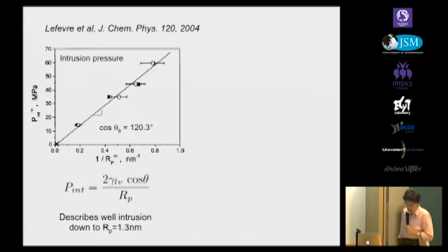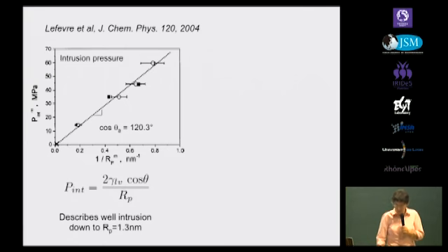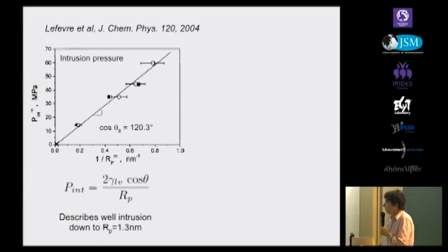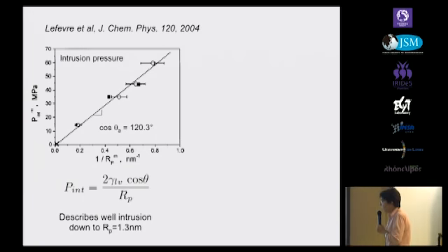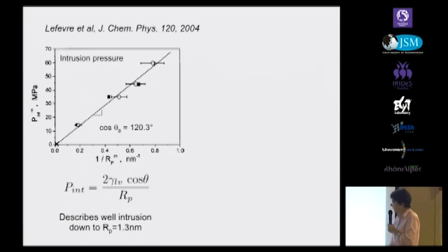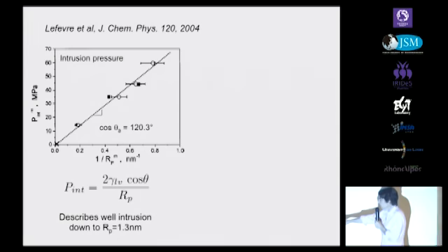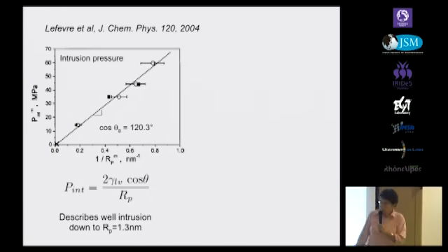What we found on these well-defined porous media is that the intrusion pressure indeed follows the law of classical capillarity and grows with the inverse of the pore size in a linear way, with a contact angle of about 120 degrees for our silane grafting treatment.